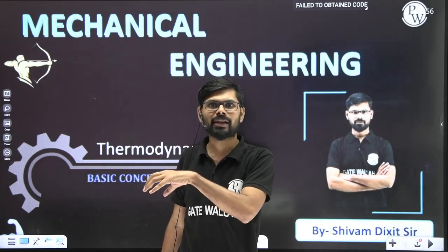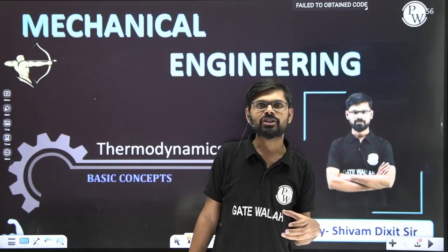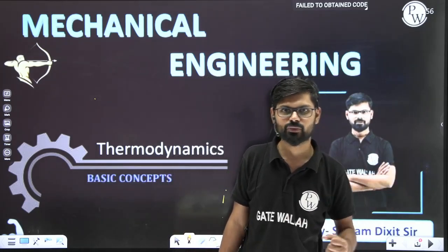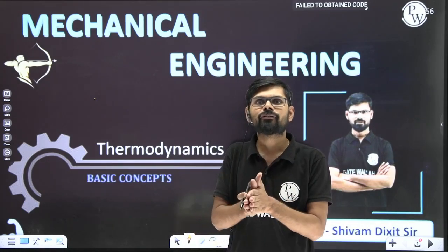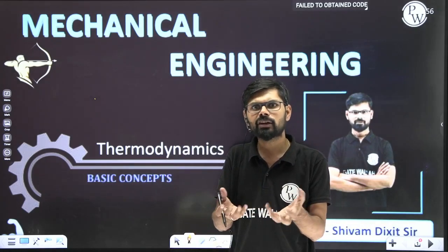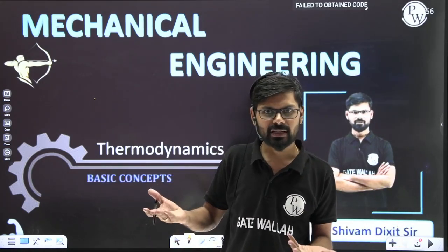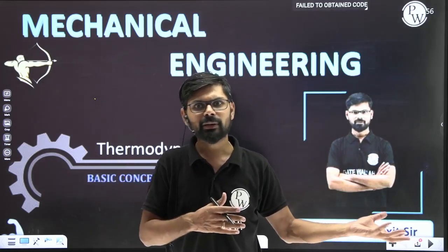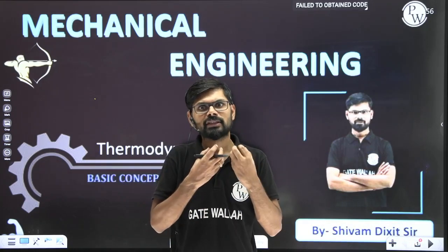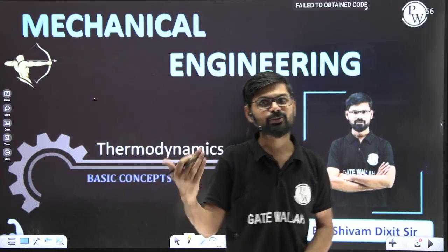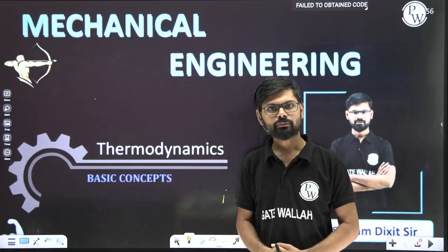But when we come to classical thermodynamics, where the aim of the subject is to convert the non-organized form of energy, means heat, into the organized form of energy, that is work, then to get work from a particular system, generally we get work due to expansion, whether it's a closed system or open system. You may have seen that IC engines are there. Here the piston is expanding and we are getting work, correct? The same thing is happening in a turbine also. In a turbine, the steam is going to expand and we are getting work. So basically we are getting work due to expansion, means increasing the volume.